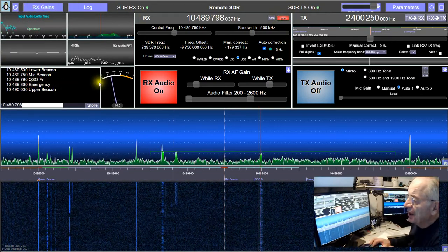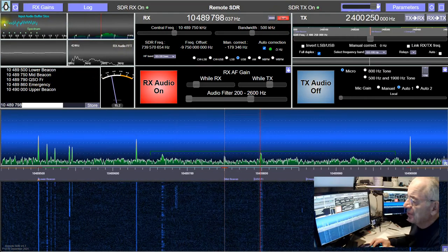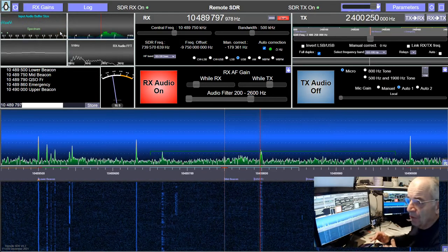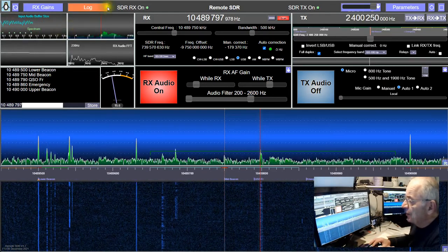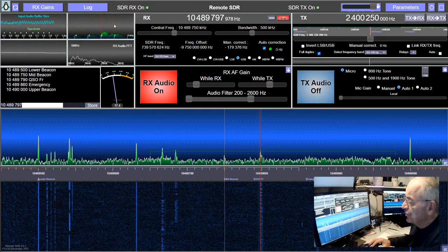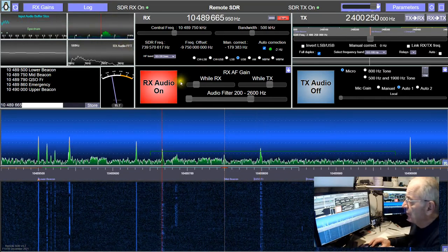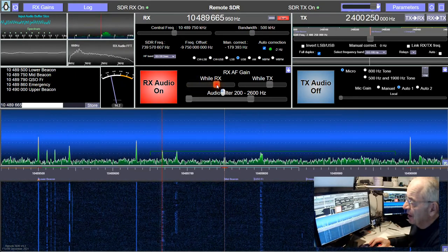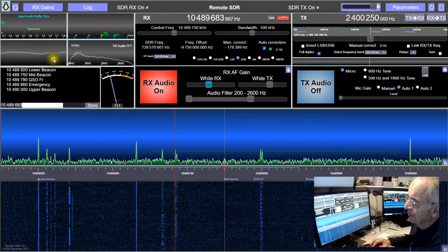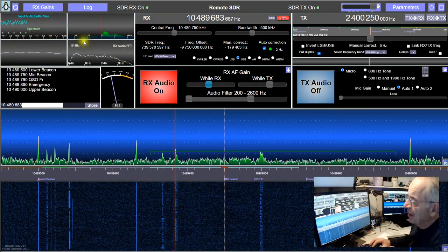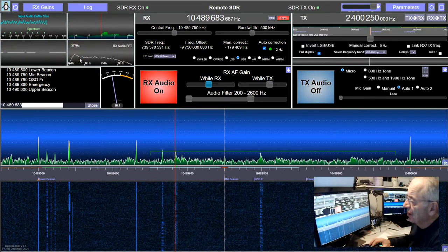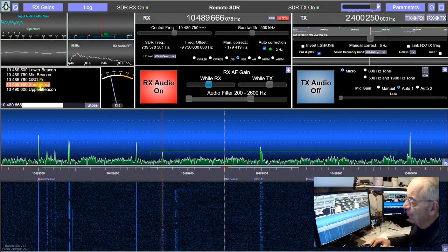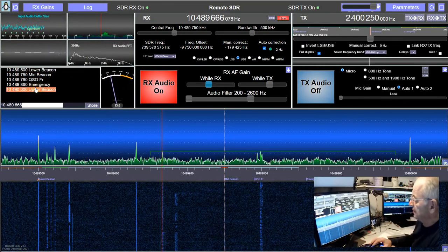On the left part here we have the control of the complete system. We have the flow of data represented here, received from the Raspberry Pi to the web browser here in my office. You have also a zoom around the audio channel of the spectra. If I increase the audio level, I have here the temporal representation of the audio channel and the spectral representation of this same audio channel. We have also an S meter here and some preferred frequencies which I mentioned here.